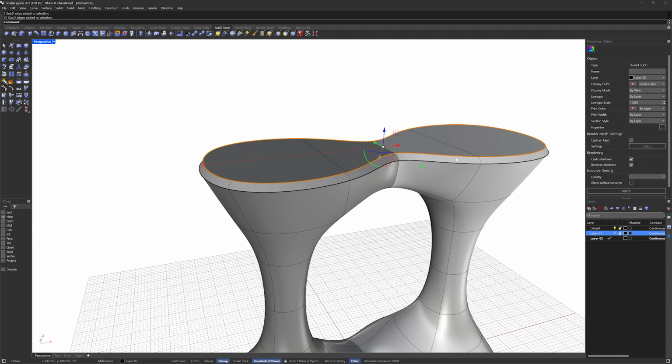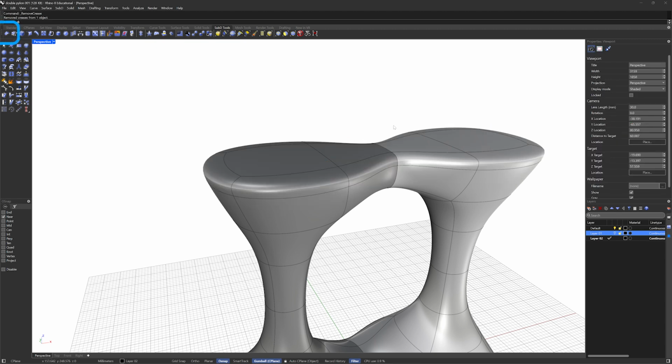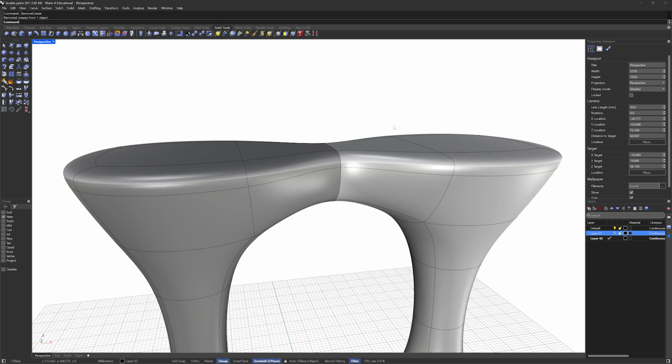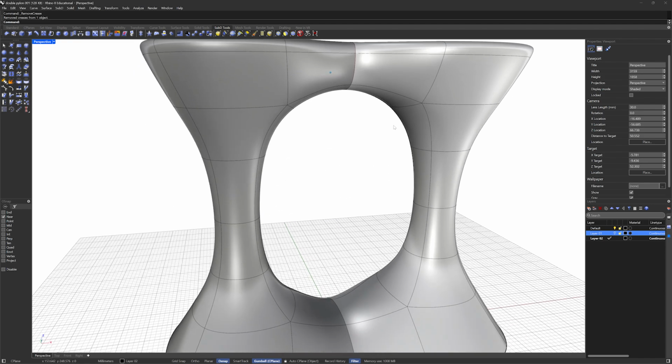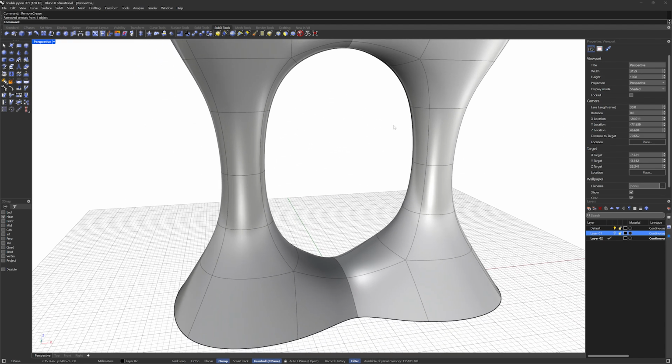Now, of course, the crease is still there. Let's fix that. Double-click, and we're going to go over to the uncrease. There we go. So now we can appreciate it. So this process of adding creases and removing creases and then putting bevels in, I think, is a great workflow to keep the edges sharp because they're easier to work with.